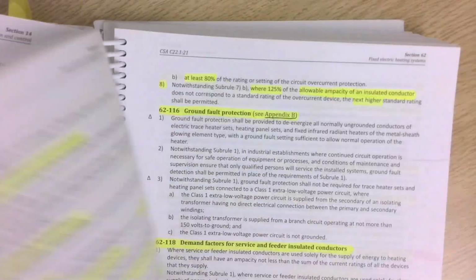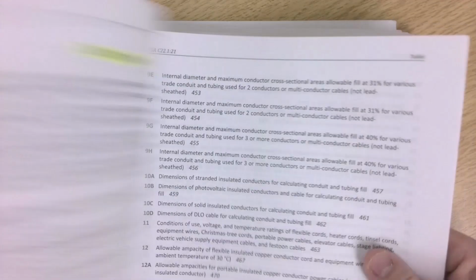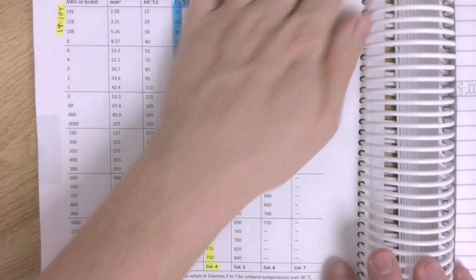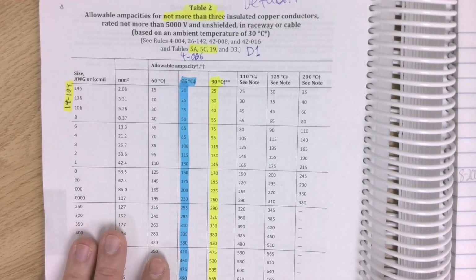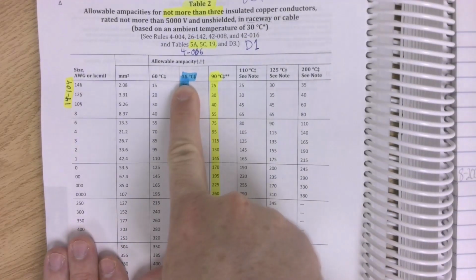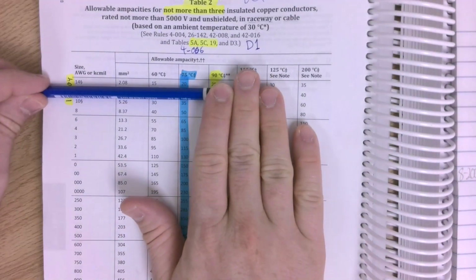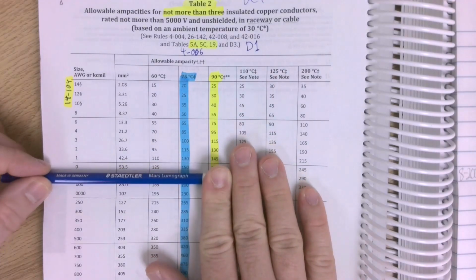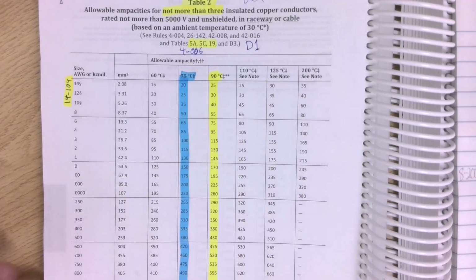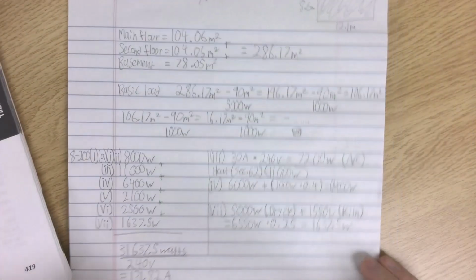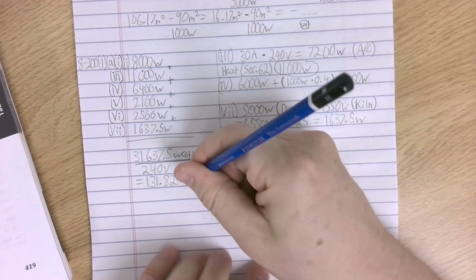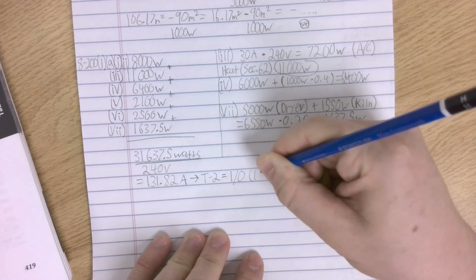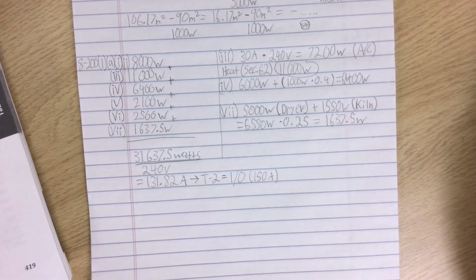And so we're going to go to table 2. Should be able to find it. It's pretty well worked in the codebook. And we're going to remember that the question gave us 75 degrees Celsius termination temperatures. And so we're going to look down the 75 degree column and maybe use a pencil to keep ourselves lined up with the right conductor size. And 1 gauge, nope, too small. And we're going to go to a 1/0, good for 150 amps. So I'm just giving myself, yep, this is what I did. I went to table 2, which gave me a 1/0, good for 150 amps. Cool. And now I'm going to size my overcurrent.